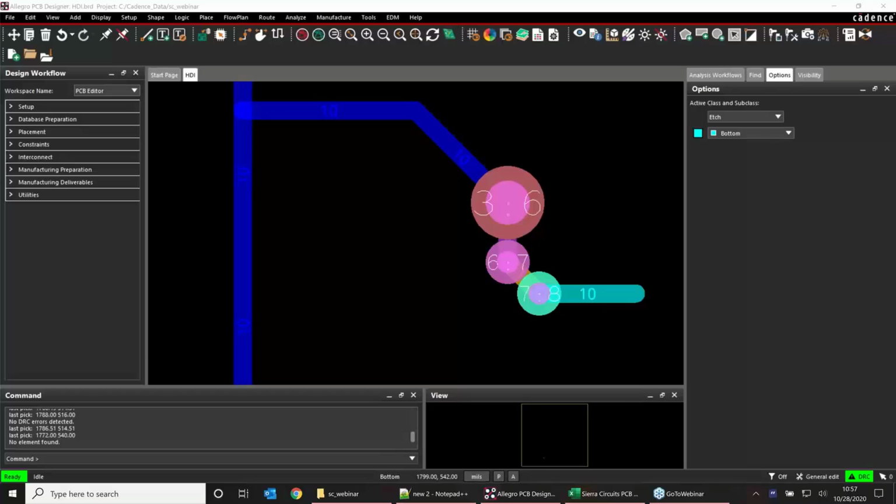Because if you choose 5 mil for the differential impedance, then theoretically you should require infinite separation, because those two lines will become virtually two single-ended traces without any coupling. The whole idea of differential pairs is to allow some amount of coupling between the two lines, and therefore the trace width there is always different from the single-ended trace, whose impedance is half that of the differential impedance. So the answer is yes, the two lines should have different widths.